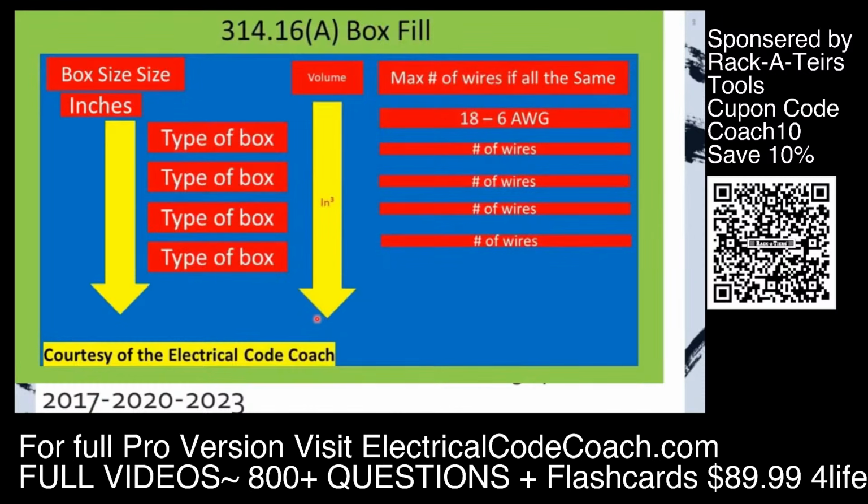The next column that we need to pay attention to is this middle one right here. Now, in the NEC, it actually says a minimum volume, which is kind of deceptive to the installer because it's actually your maximum volume that you're allowed to fill that box. And it's listed in cubic inches. That's all we're concerned with. We're not concerned with any metric designators inside of this table.